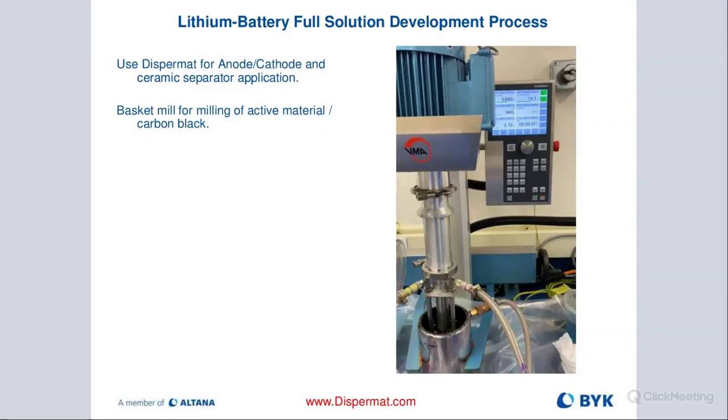Temperature control is critical. And you see here on this picture, we actually have temperature control of our basket mill. You see these two jackets right there on the shaft of the unit. That's the mill head right there that's immersed in the container. And right above it, we have these bars that are holding the mill head. They are hollow, and there are cooling channels that go in and provide the cooling fluid to ensure that we maintain the appropriate temperature.